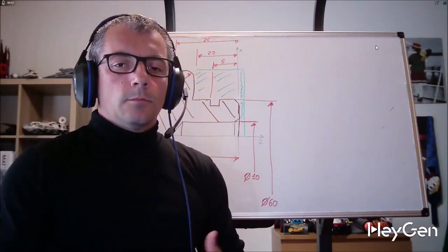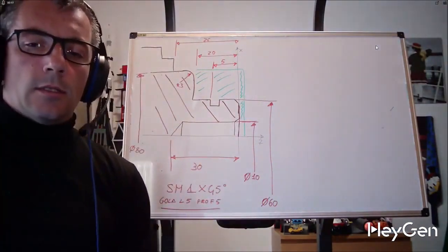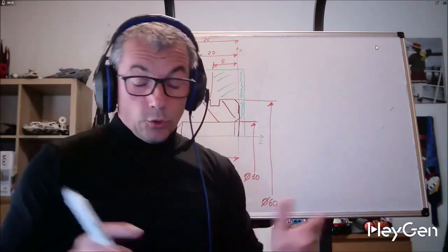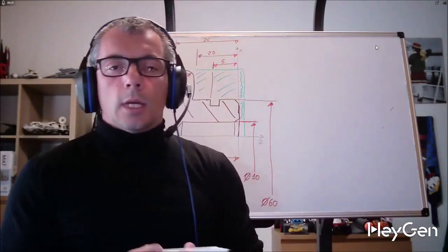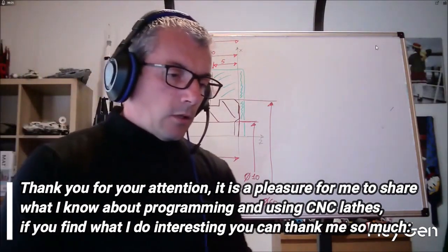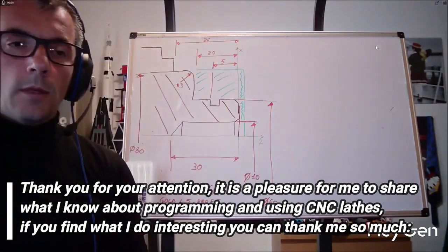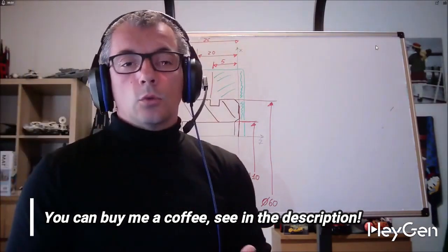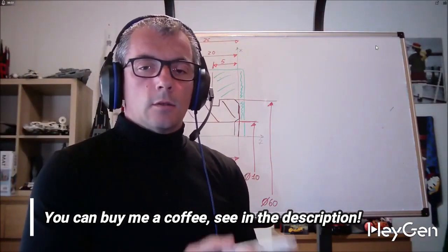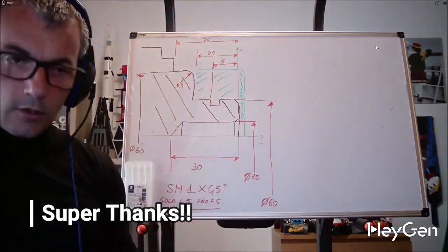We continue with our tutorial on CNC turning machine programming. So, we have seen in these videos that we can move in G0, G1, linear interpolation, by entering two coordinates and creating an inclined line according to the arrival point X and Z, or according to the angle.